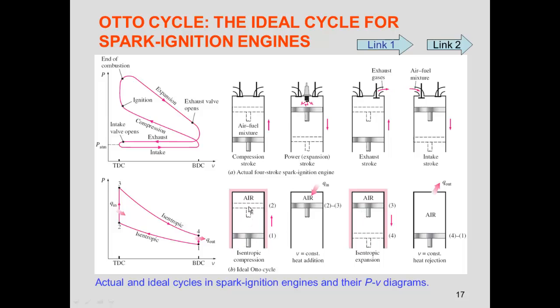Because of that heat in the air, we increase its pressure, and we are going to expand the piston. This first piston moving up, we call it the compression stroke. Each stroke is the movement between the top dead center and the bottom dead center, and vice versa. So in this expansion stroke is where we move the piston down, also known as the power stroke, because this is the stroke in which we are going to get power. And then we are going to reject heat at constant volume.